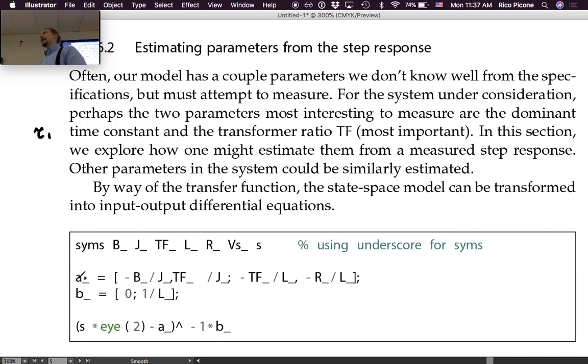You can actually estimate the damping this way too, and I was originally going to have you guys do that, but then I actually did this analysis, and I discovered that the sensitivity to parameters changing for the damping estimate is really bad. So your uncertainty would be horrible. I didn't want to make you guys estimate a parameter with a huge uncertainty associated with it. Probably the spec sheet's value is better. So what it means is not that you can't know that value. It just means that this isn't a great way to estimate it if your measurement is very sensitive to changes in that parameter.